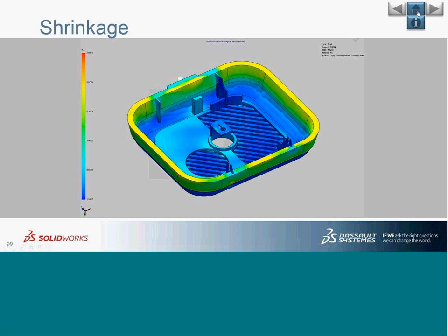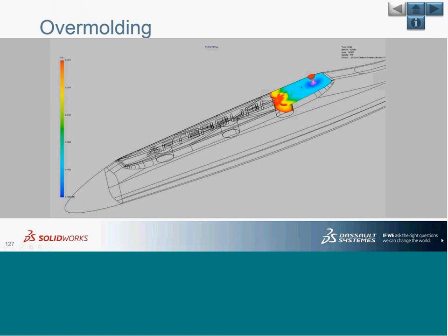Next is insert molding. I mentioned today I'll be covering an example on this one as well, wherein a certain plastic is already injected and cooled down, and we are injecting one more plastic to cover some other area of this particular component. It could be a case where there are metallic inserts or other components not created by plastic injection, and now we are going to inject plastic into the rest of the part. So here we are going to use overmolding. We'll see this one today.